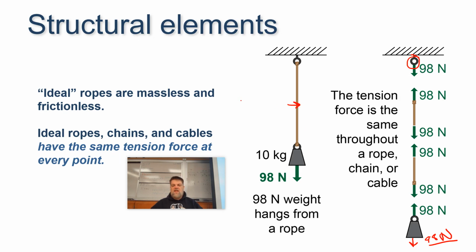So if it breaks right here, if it's a steel cable, it could be rust, right? And if it's a chain, maybe it's a bad weld, because they weld those chain links. And if it's rope, maybe it's frayed.